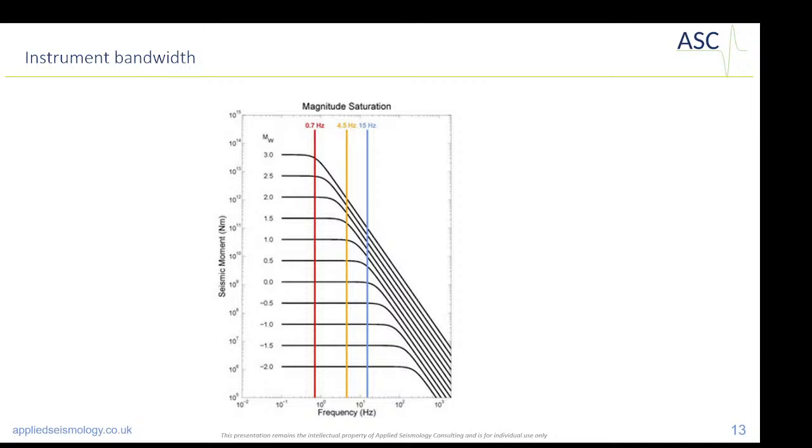These high frequencies are easily attenuated. So if we're interested in monitoring events of very small magnitude, what we will want to have is an instrument that is sensitive to these high frequencies. Typically, we can see here, we would use this 15 Hertz instrument for them, because basically it has a flat response above it, and below it there's not much energy because most of our energy is in the high range of frequencies. And we're talking high frequencies here, anything above tens of hertz in the field.